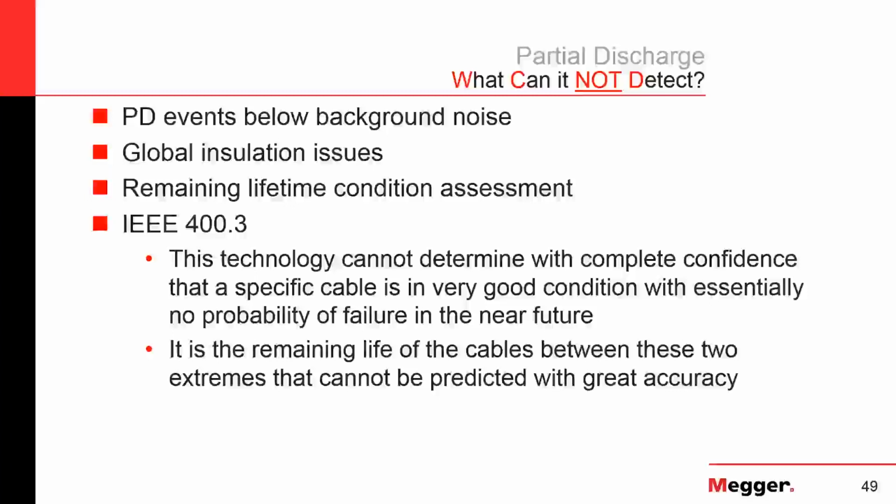So IEEE says this technology cannot determine with complete confidence that a specific cable is in very good condition with essentially no probability of failure. I mean, that statement is talking about absolutes. Nothing's 100%, so that makes sense.